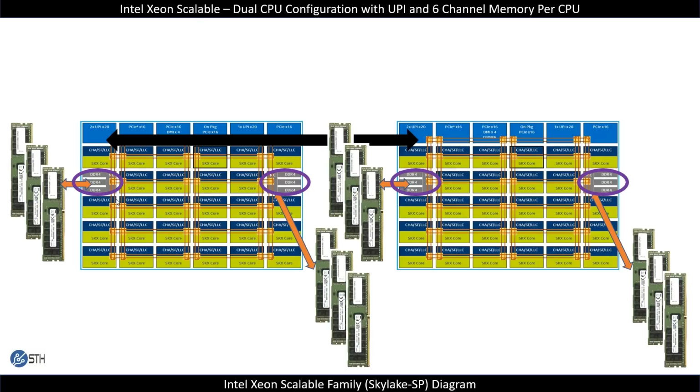So here, Intel only has 2 memory controllers on a die. Each one can accept up to 3 DDR4 lanes, and each DDR4 lane can have up to 2 DIMMs per channel, and so you get 6 DDR4 lanes total per chip, and up to 24 DDR4 DIMMs to connect.